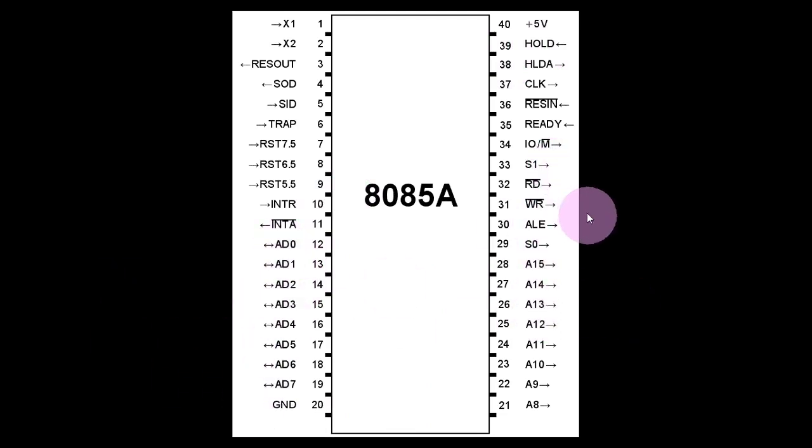Now the data will be transferred between the externally connected device and the memory directly, not using the internal registers of the microprocessor. So the microprocessor will have no role to play, and the data will be transferred at the speed at which the peripheral is working. So that is the meaning of the HOLD and HLDA pins, and they are considered control pins, right?